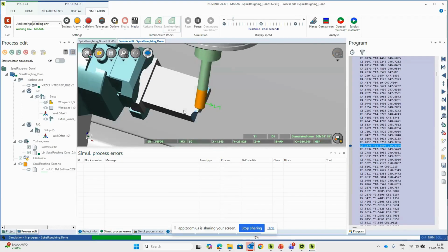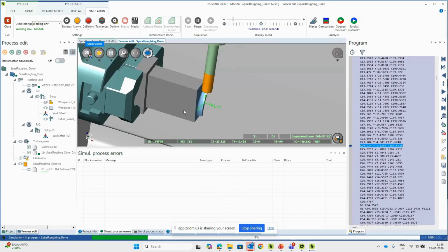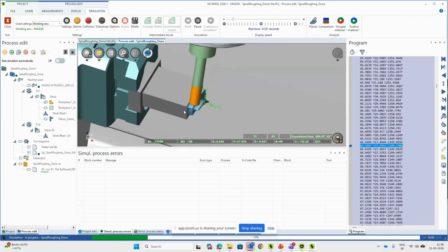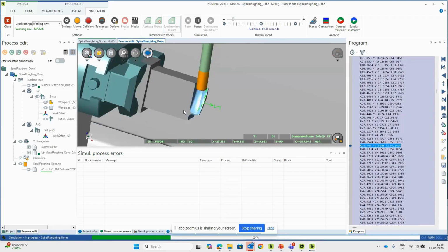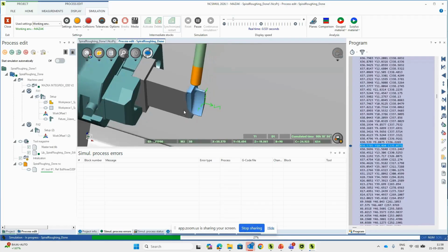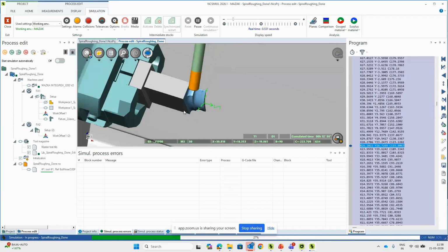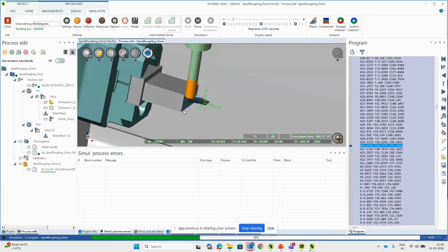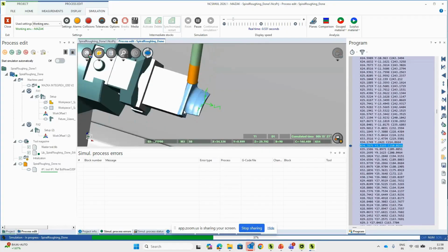So this is what we used to call the real simulation, because simulation, yeah, of course, I agree with that. That is a tool path simulation. You can get it from your CAM software, but the tool path, after you select your post processor and generate your NC, and that NC is going to be a real simulation on your CNC machine. So we should understand what is the real simulation and what is the tool path simulation. Real simulation is nothing but our G code based simulation, and whatever simulation we are seeing inside the CAM software, that is a toolpath simulation.